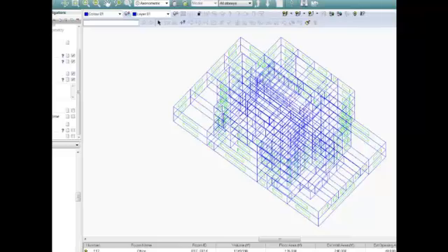And some of the tools that you'll see underneath here are actually available inside of Affinity. So some of the things that we looked at with climate or building metrics, and then also with the building heating and cooling loads. We also were able to compare our building in Affinity against the 2030 challenge, which is looking at different reduction levels depending on what year you're doing that analysis in. So there's quite a bit of features inside of the tool.